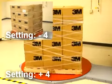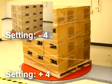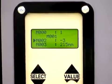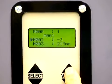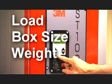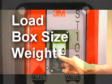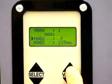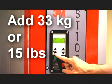The factory preset value F creates a crossover every 330 millimeters. The M002 setting is determined by the pallet load, box size, and weight. Heavier and smaller boxes may require more crossover X's. As a guide, use the factory preset F for boxes weighing 33 kilograms or 15 pounds.